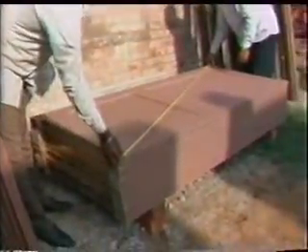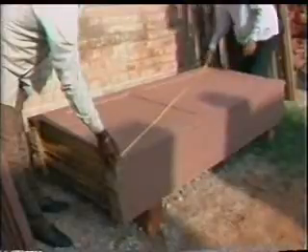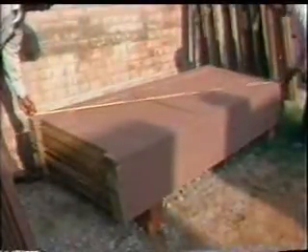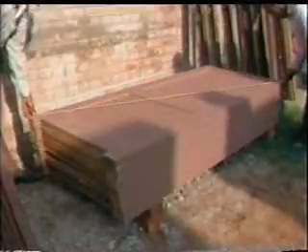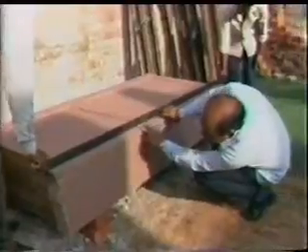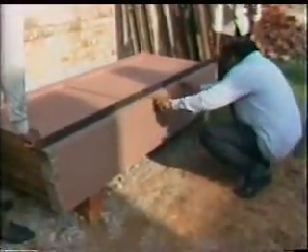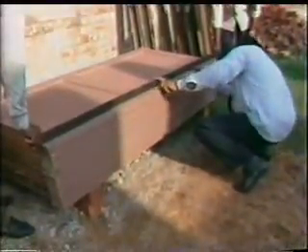There should be no difference between the two. To check that there is no warp or unevenness in the shutters, put a steel straight edge over its surface and check for gaps all along the straight edge.